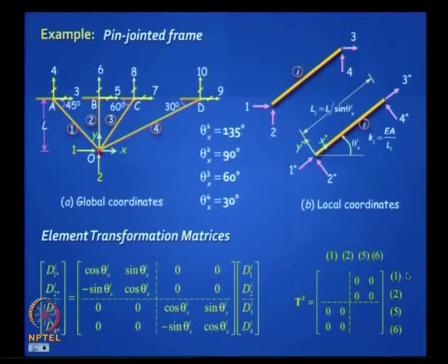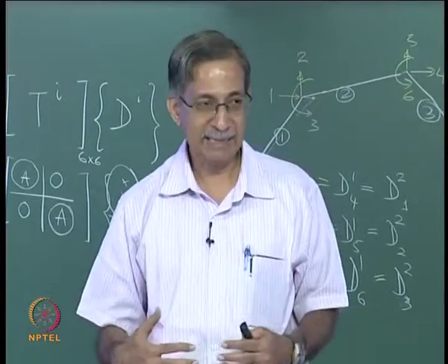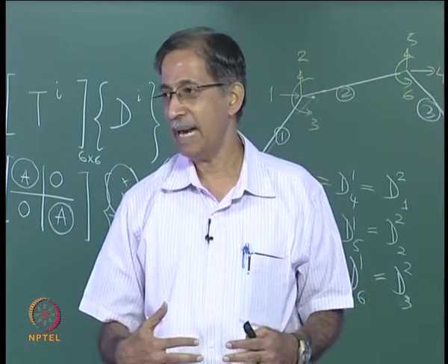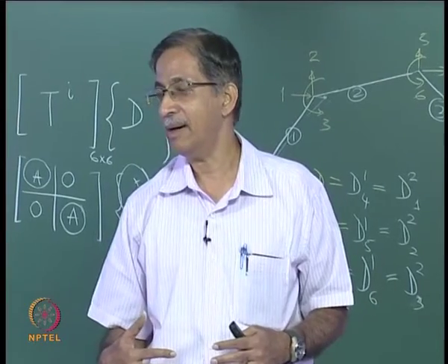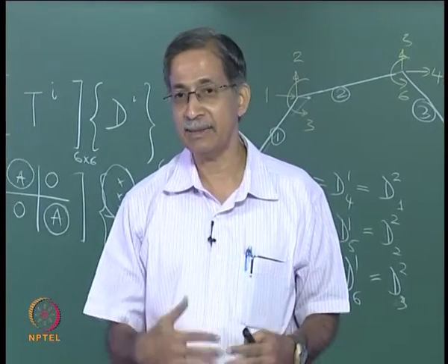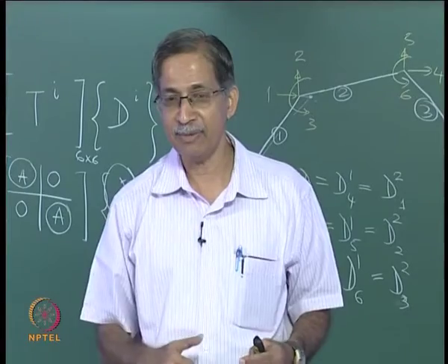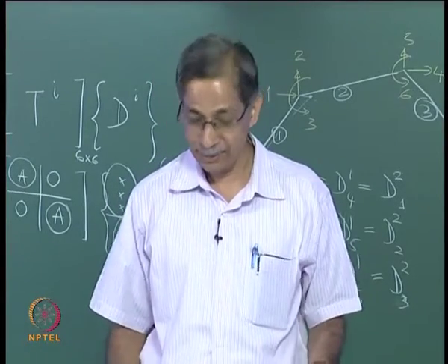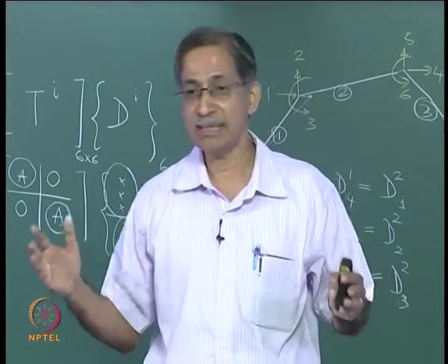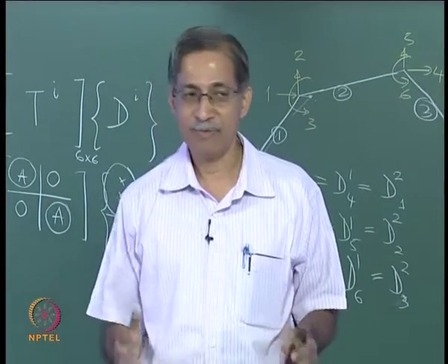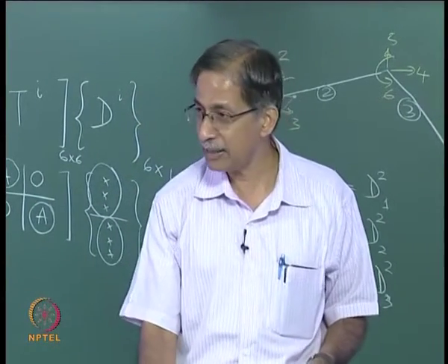This is a clue for me that the displacements that I get at the element level are the same as the displacements I get at the global. No plus here, be careful. It is exactly equal. So it helps me assemble my structure stiffness matrix from my element stiffness. Is this picture clear to you?